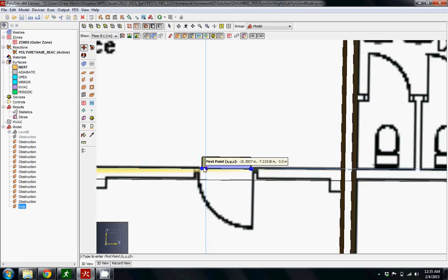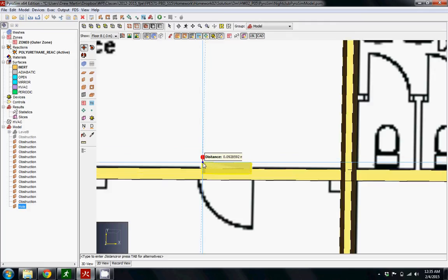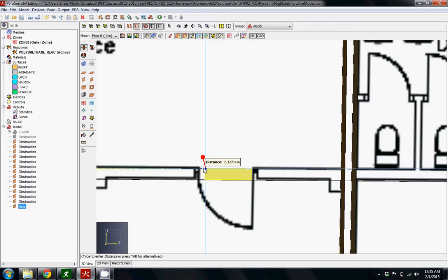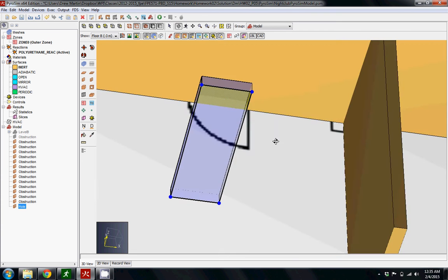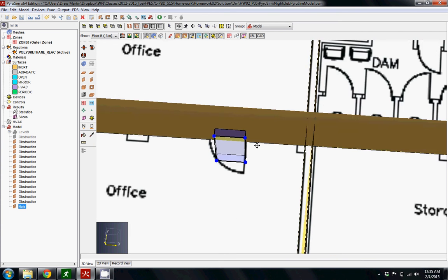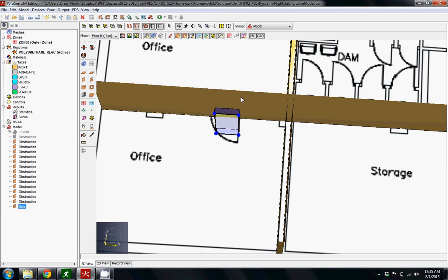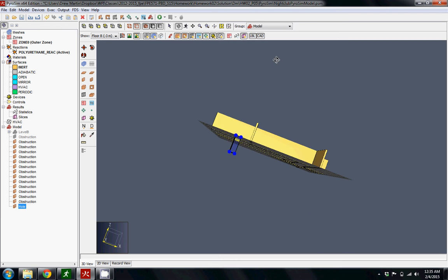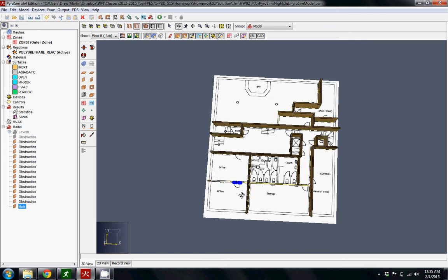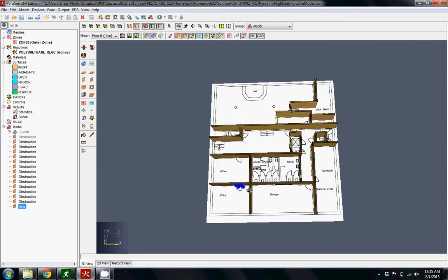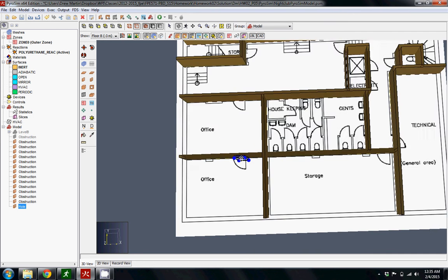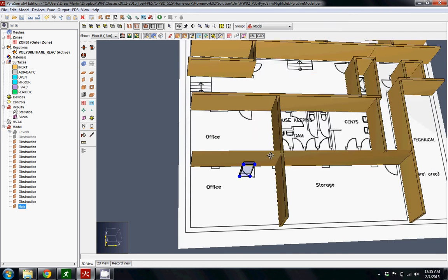So we just click on that. We have the object selected already. I usually click on one of the corners because it's easier to control, and we can just translate it into the door frame like this. Let's take a look at how that worked. We can see that it didn't work out too well because it translated in the z direction as well as the x direction.